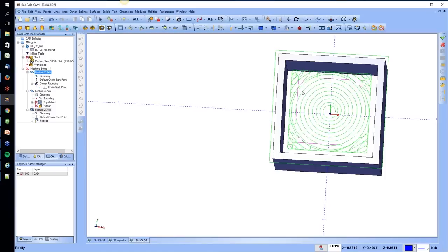I mean, it's always easier to cut with a bigger tool and then have a tool come in with a smaller diameter and go into the areas that the previous tool couldn't fit. That alone is going to save you time. So start looking at these toolpaths as, okay, just because they're categorized as 2, 3, doesn't mean I have to only use it for 3. I can use it for 2, okay? So go into those, start playing with those.